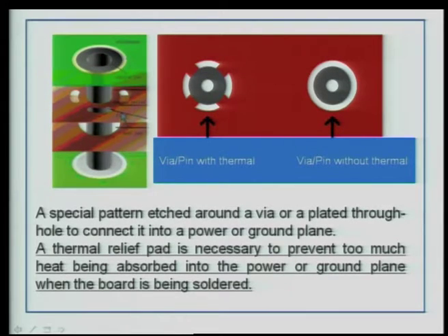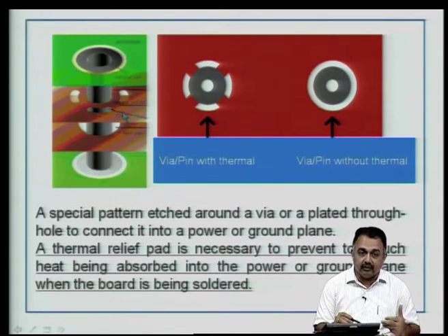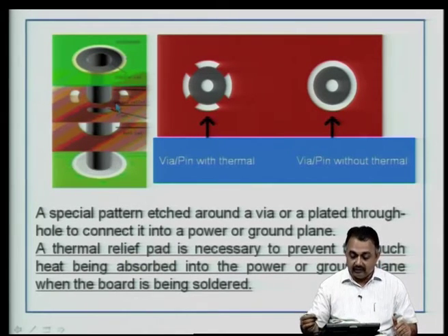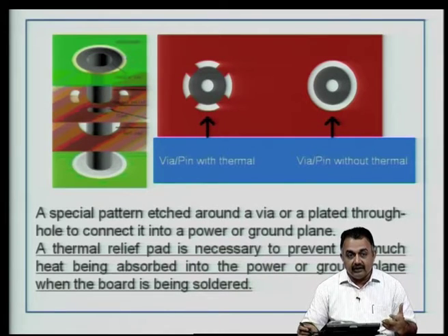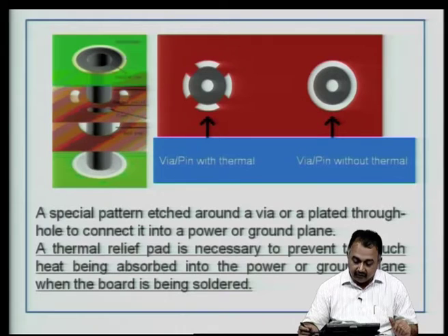component. What happens is that your structure gets damaged, your board gets damaged, your component gets damaged, and therefore, to prevent that kind of situation during manual soldering, you provide this thermal relief, so that the heat that is absorbed is not too much and heating takes place quickly to melt the solder and enable good soldering and get a wet solder for your component.